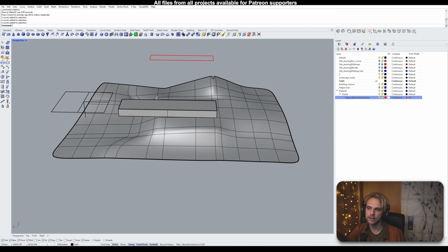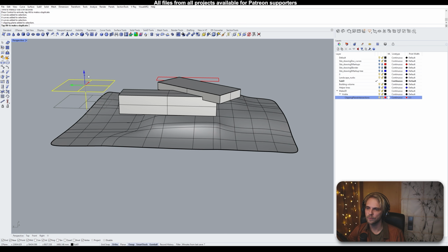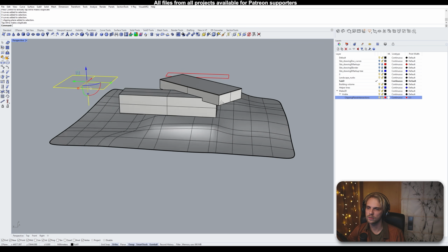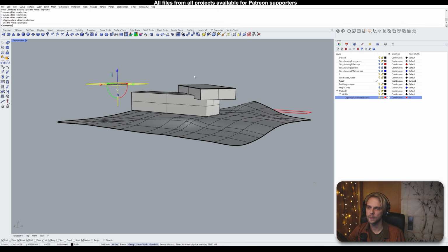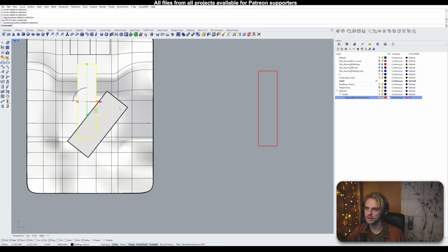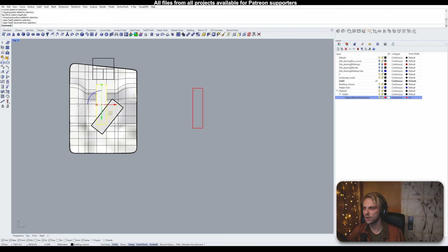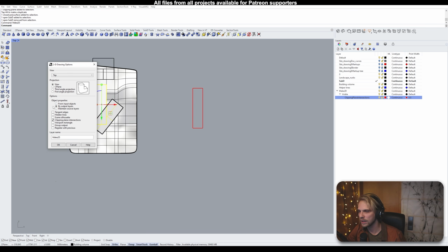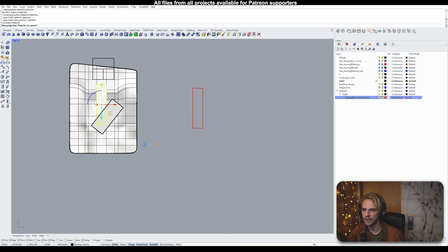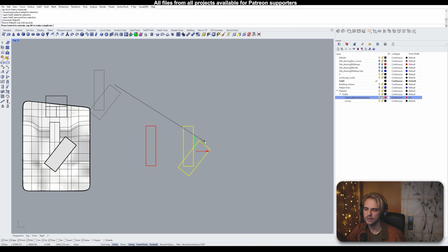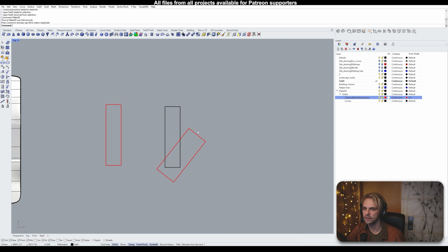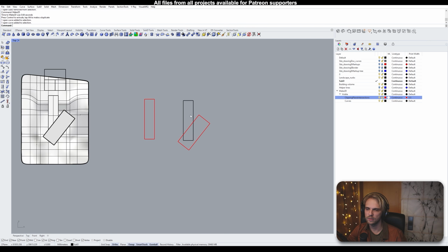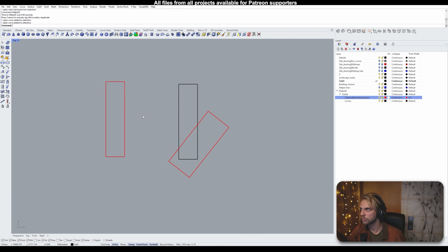Now, if I go back in here and I lift up this clipping plane to something like so perhaps. Yeah, that should do the trick. So that we're cutting through this rectangle here, the second floor, and I will select these two objects again. Oops, not the landscape. We don't care about the landscape at this point. I type in make 2D again. All of the settings are exactly the same. Hit OK. It generates a second geometry for me, right? So this generates my second floor plan.